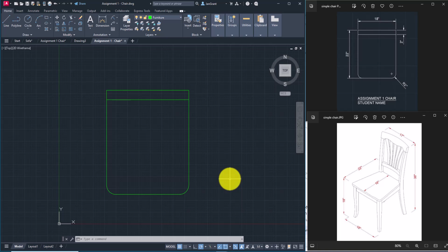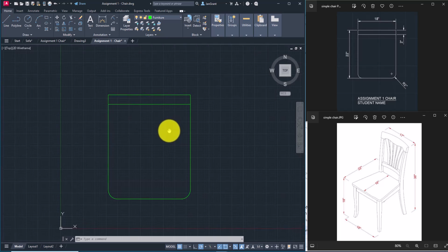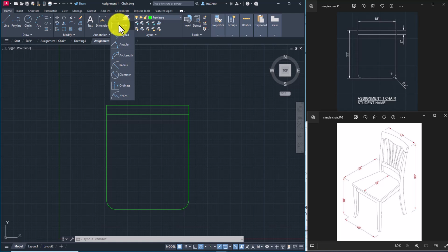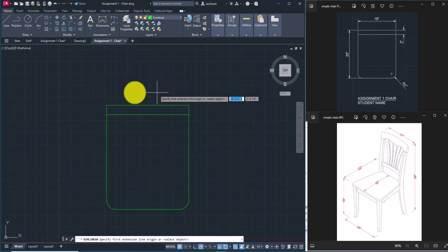I'm going to, for this assignment, let you know what the scale factor is based on already drawing it, and bring you through the commands. So we need to make a different layer current. We're done with the object layer. What I'd like to do is to show you how to move something on the right layer. So the first thing I'm going to do is place this linear dimension up here on the furniture layer, and then we'll move it to the right layer.